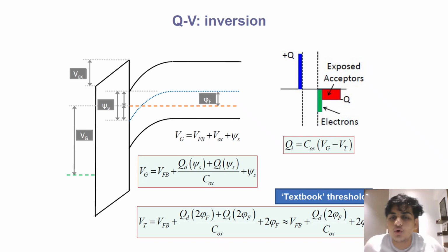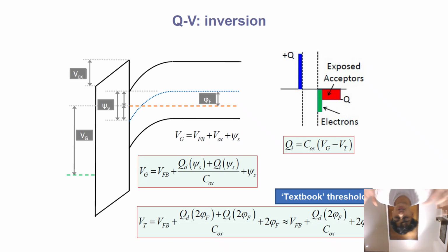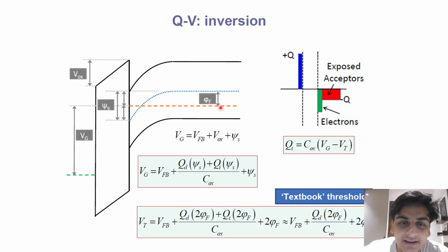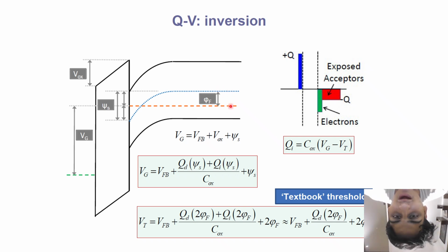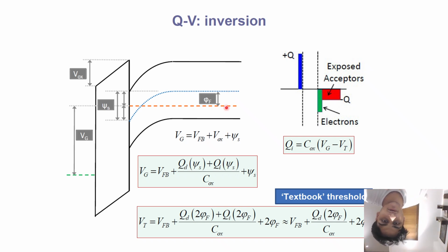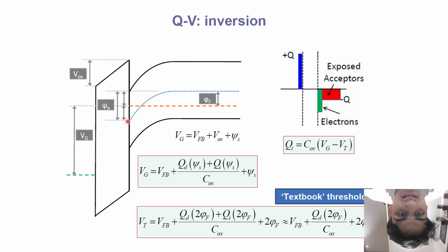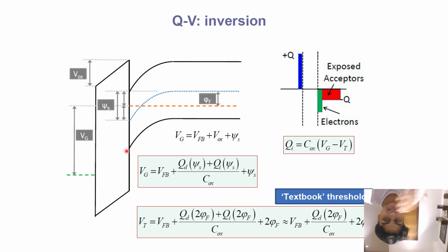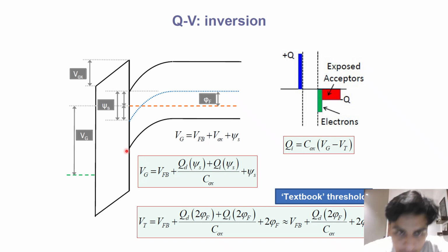We spoke about the threshold voltage, or this inversion occurring, being at the point where this part becomes more N-type than this becomes P-type. And the way to quantify that is essentially that this difference that you have between the intrinsic Fermi level and the Fermi level, if that gets equalized here, if the bands bend so much that it gets equalized here, then this is as N-type here as it is P-type here. So beyond this point, inversion, quote unquote, occurs.